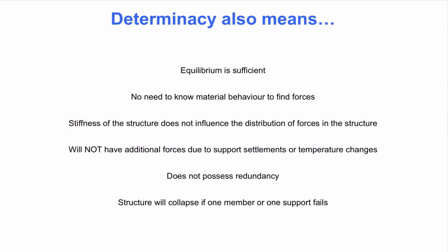Another interesting point about determinate structures is that there will not be any additional forces in the members if the structure experiences support settlements or temperature changes. In other words, the supports can move and the members can change size without any additional forces inside the structure.